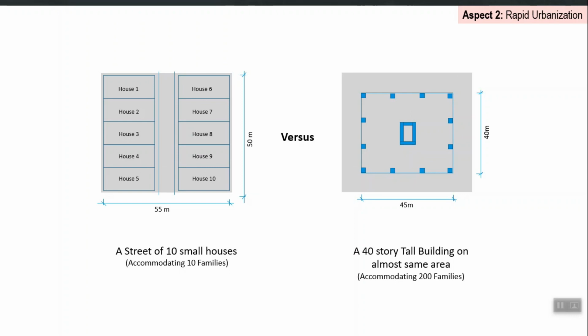He mentioned actually about the response modification factor, but there are other factors also which account for different phenomena. Now, if you can explicitly account for that phenomena in your computer model, which can actually tell where there will be cracking, where there will be yielding, or where there will be crushing, then you do not need all those factors for your design, right. So, you can explicitly check whether the code's intention is fulfilled or not by using PBD.